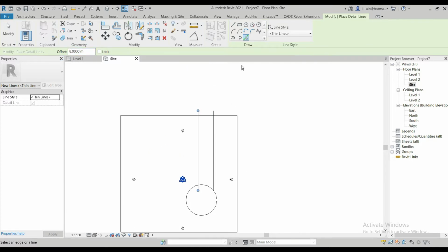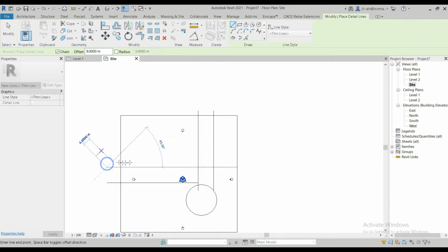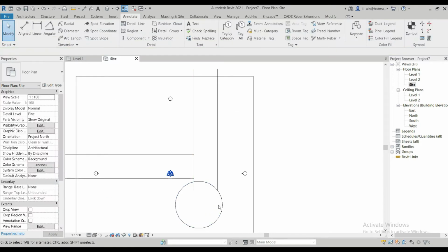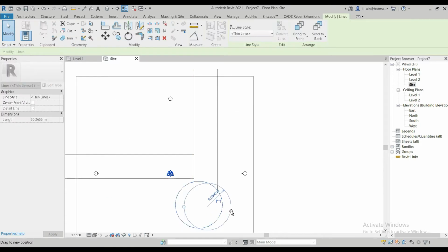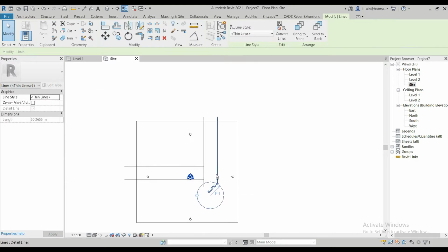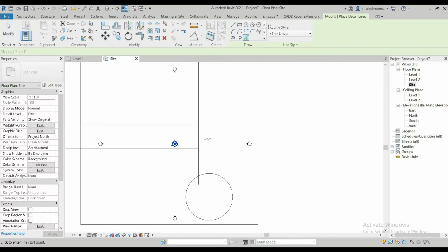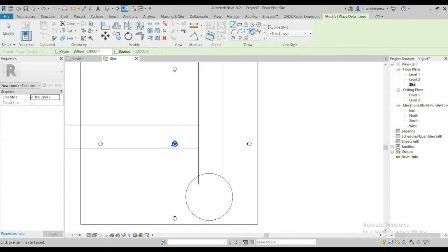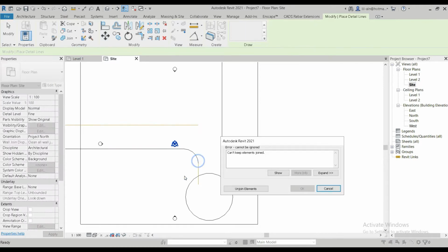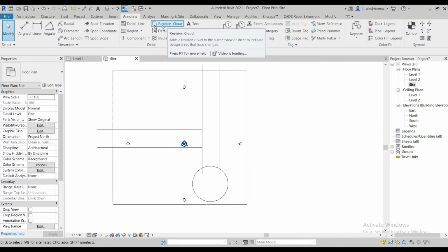The width of the road that I've chosen is 8 meters, 4 meters for every single lane. For the roundabout, the radius is 8 meters, so the diameter is about 15 to 16 meters. A single carriageway is usually around 7 meters wide, 3.75 for every lane. I've chosen 4, so a total of 8 meters is the width that we're taking.